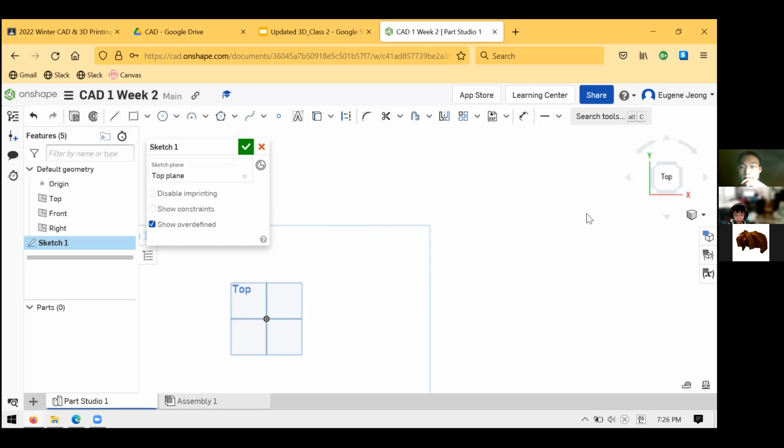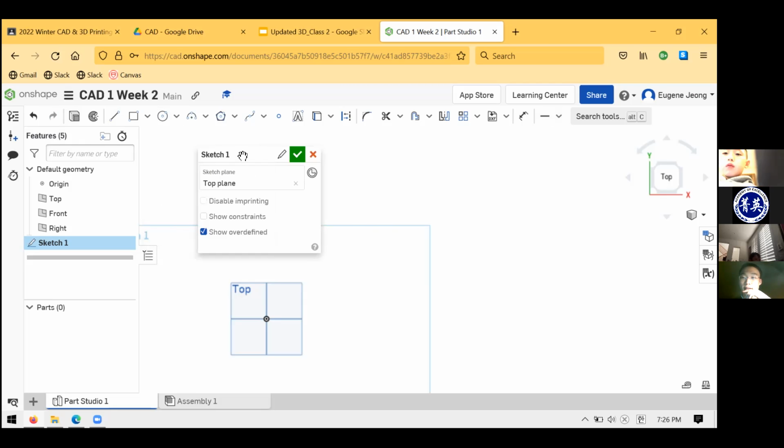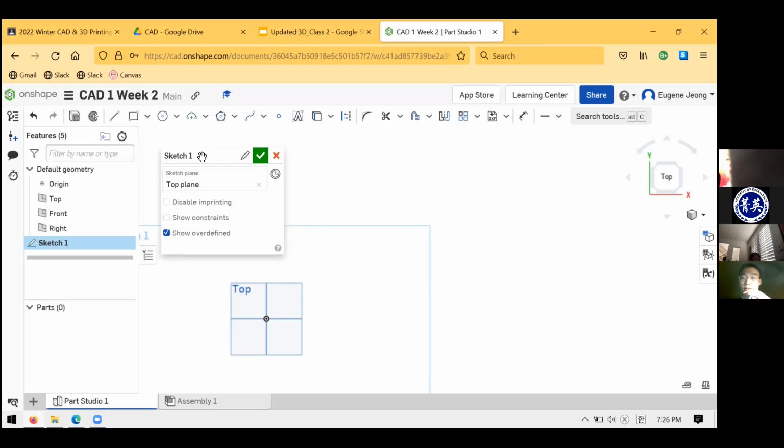Do you have a question, Leo? Yeah, when I go to the search, it only has line, corner, rectangle, extrude, and revolve. And when I search for horizontal to see horizontal. So if the tools you have are extrude, revolve, and so on, make sure that you're in the sketch workspace right now. Because if what you're seeing are mostly 2D.